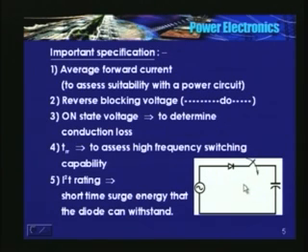What happens? A large surge current will flow because the voltage across the capacitor cannot change instantaneously. It was 0 just prior to closing the switch, and this is at the peak.